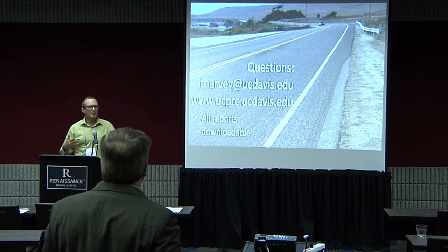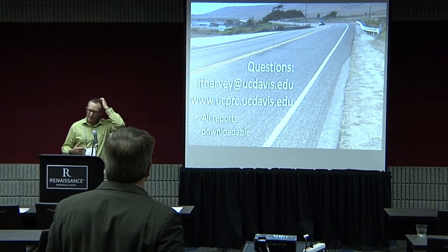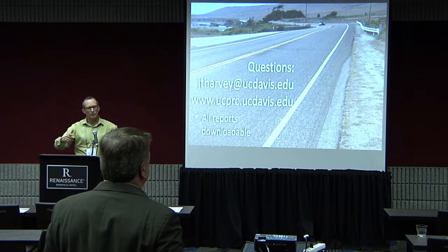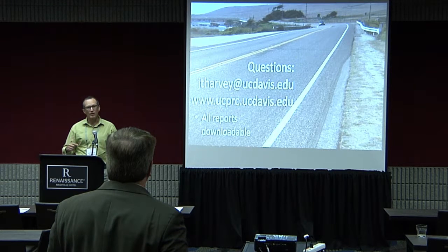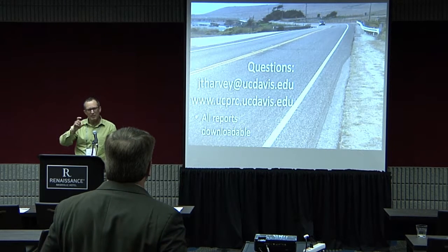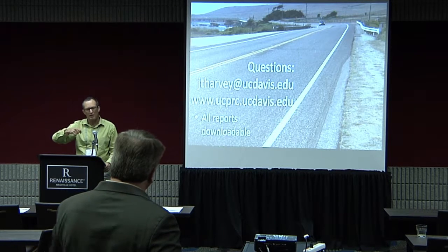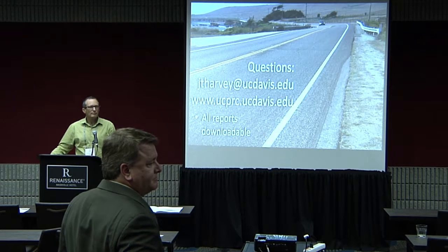When I've talked to him about this, he said he's not getting as much of a difference between the rubberized, and they use a lot of polymers. So Florida's going more with polymer modified, open graded, and I think to some degree conventional. They haven't seen as big a difference as we had between our rubberized and our non-rubberized in terms of durability and raveling performance.